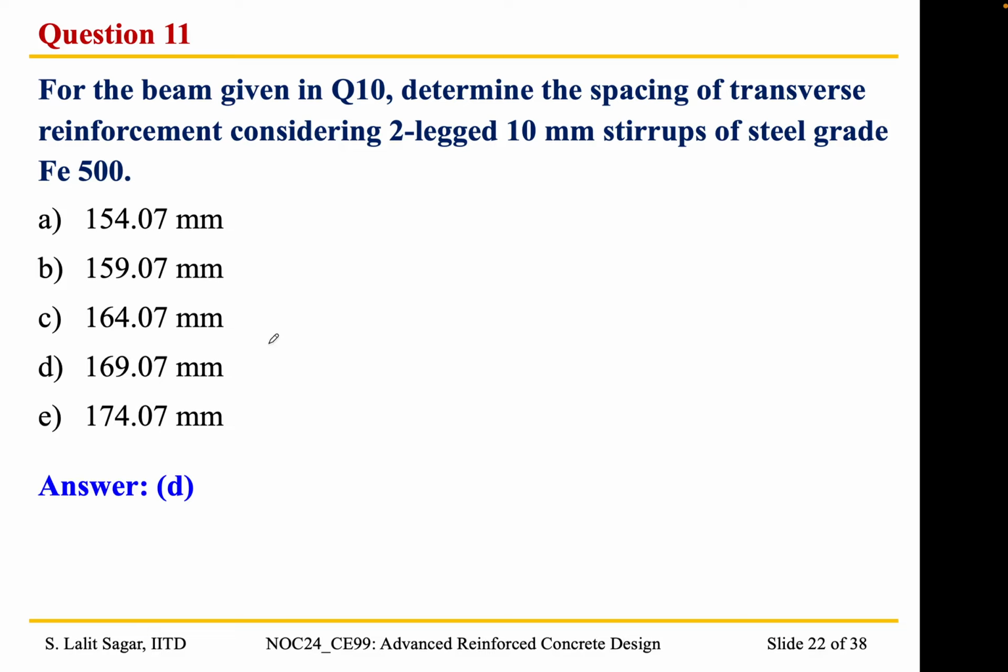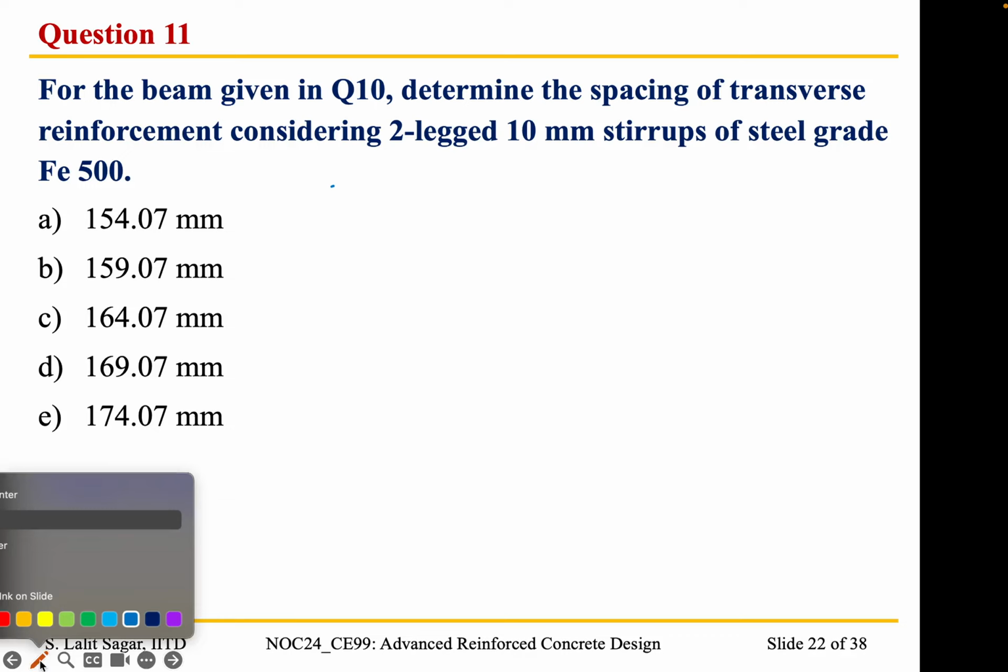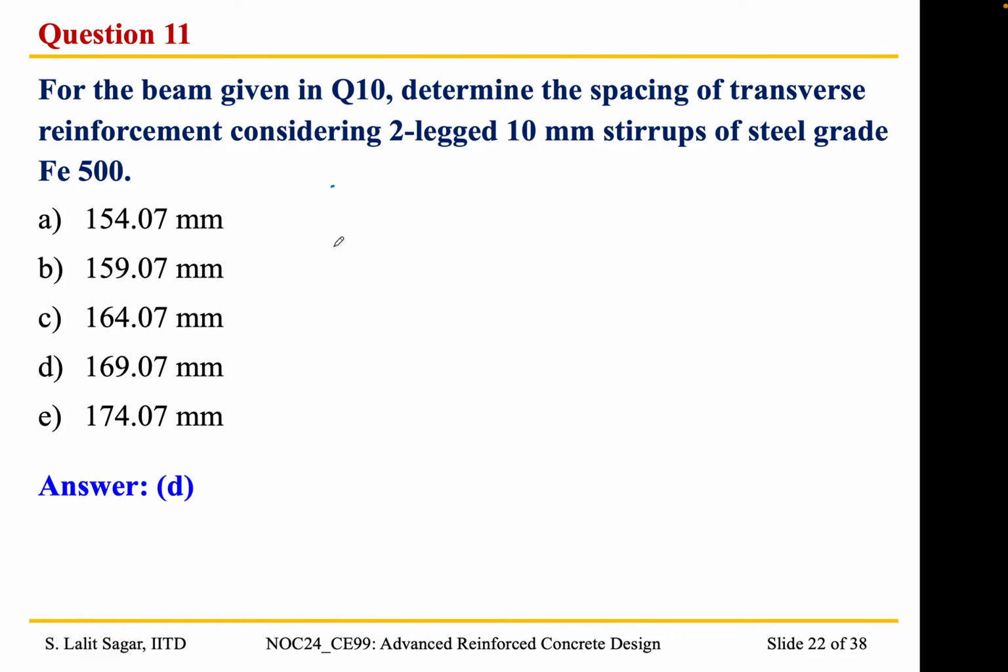Right. So I'm going to write down the steps since it is the first problem where we are designing the beam for shear. So here, okay, I'll take a different color. So I'm going to write here in the form of steps. So step 1, basically we drew the SFD, right?